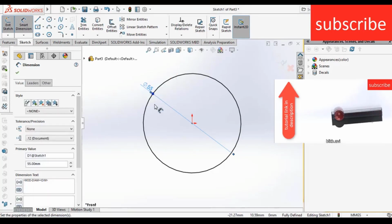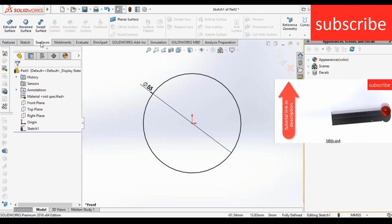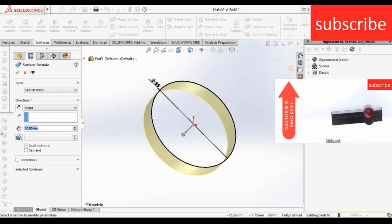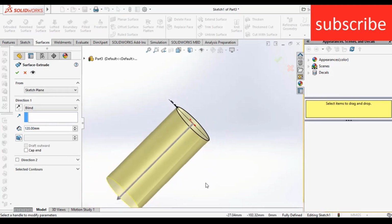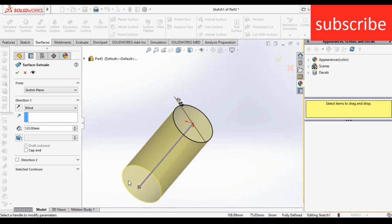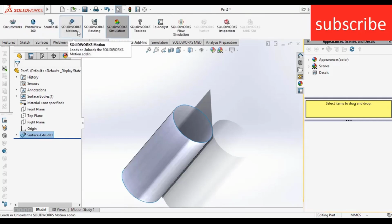You can change the diameter as per your requirement. After that go to surfaces, click on extrude surface, enter the value 120 mm or above as per your requirement. Remember, I am just going to make the cylinder of the can, not the top or bottom face, because I am going to run the simulation on this face. Okay, click OK.